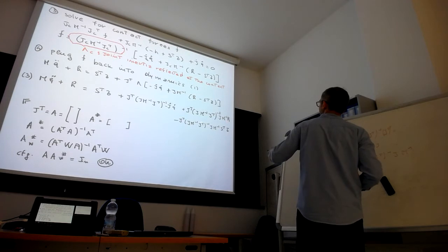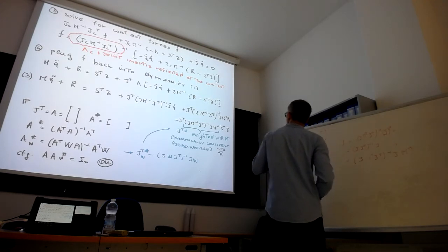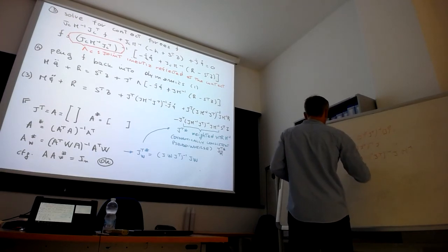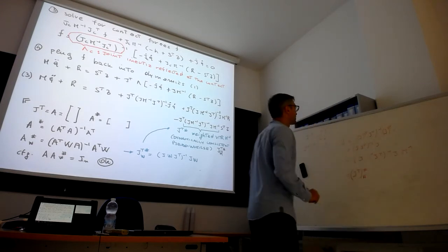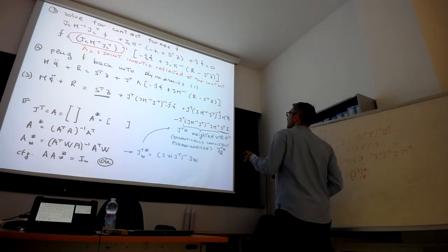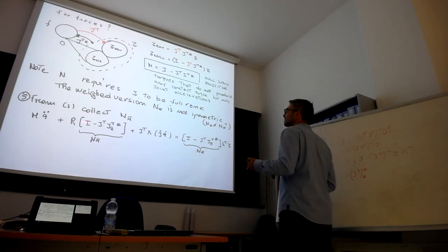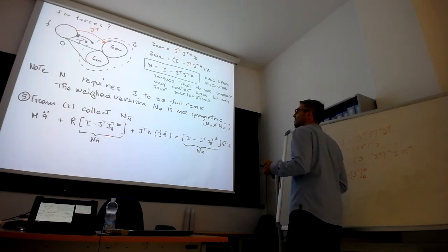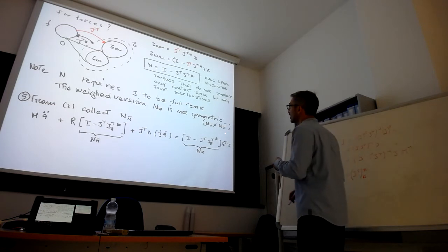Okay, so now if we collect, and we call this term the dynamically consistent Euler inverse of J transpose, where we weight with the inertial matrix. Now if we collect this term and this term and this term and this term, sorry, yes, this term and this term and this term and this, we see that we are getting something like this, which really reminds me of the null space projector for the forces that we computed in the lecture on operational space.